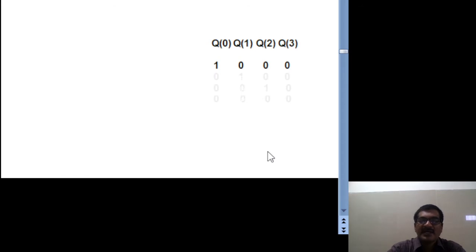Here also I am considering a 4-bit shift register, initially containing the value 1000. Now if you apply 1 bit shift towards the right hand side direction, the new result is 0100. The decimal equivalent of the original value is 8, and now the decimal equivalent of the new value of the register is 4. That implies it is divided by 2. So 8 divided by 2 equals 4.